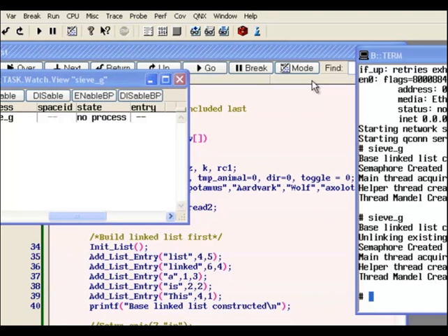Now if you have an application, a small application or process that exits quite often and you restart it over and over again, then you can use the watch system, and the watch system then checks automatically the restarting of a process, and if it is restarted it automatically reloads the symbols to the correct addresses and resets the breakpoints onto the main entry point.